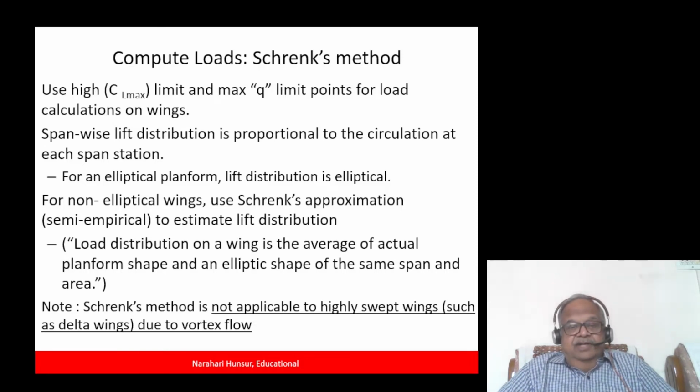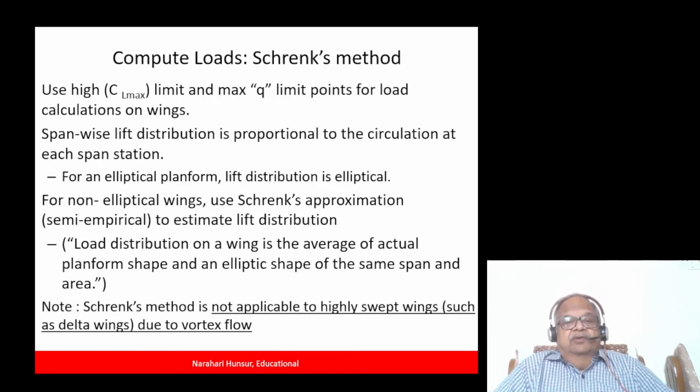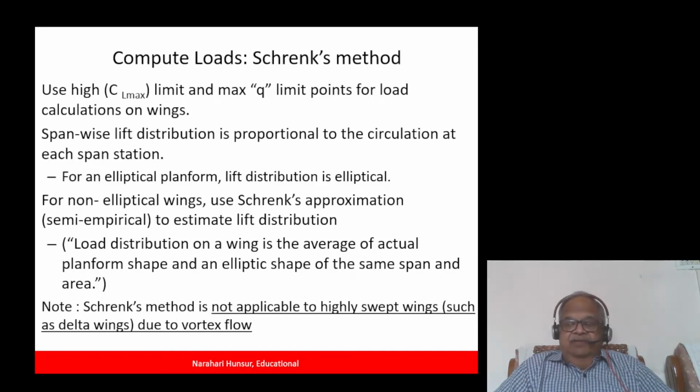Just as a matter of interest, the Spitfire aircraft, which was very successfully employed by the British during World War II, had this classical elliptic planform. But later it was realized that fabrication was a challenge for an elliptical planform, and it was quickly found that a tapered wing was as close to an elliptical planform as possible. Roughly a taper of 0.25 to 0.3 would give you as close to an elliptical planform as possible. And since it's only a taper, it's pretty easy to lay out and fabricate. So now nobody uses elliptical planforms anymore, but the elliptical planform is the most efficient aerodynamically.